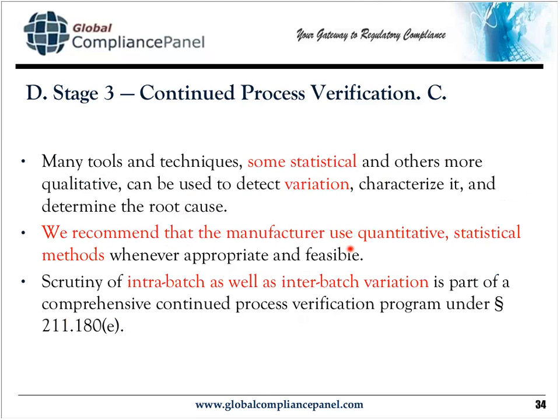They recommend that you use quantitative statistical methods, again, wherever appropriate and feasible. You want to look at intra-batch as well as inter-batch variation. Now remember that you're looking at variation within lots as well as from lot to lot. So both sets need to be monitored. And let's face it, you cannot see intra-batch or within batch variation unless you take more than one sample.